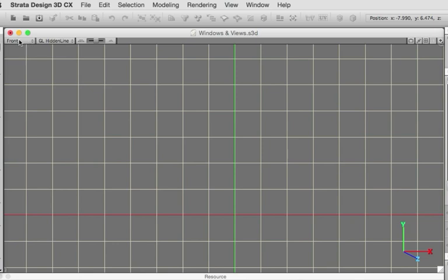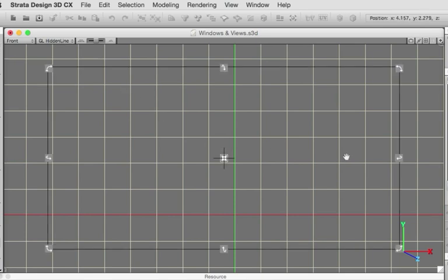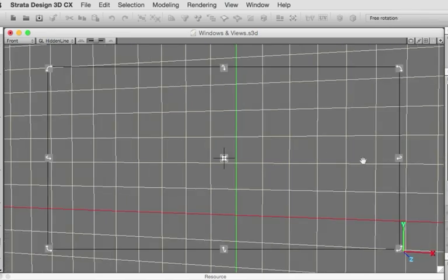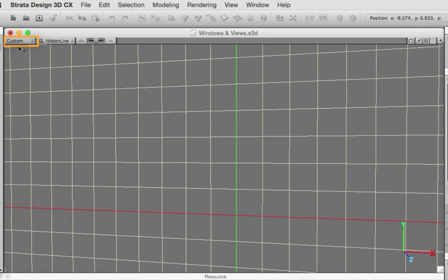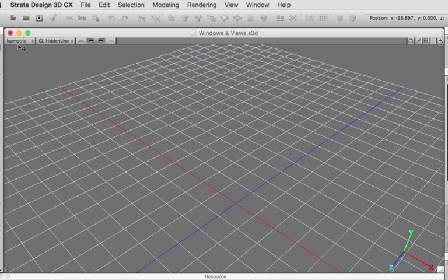You'll remember that you can always create your own custom view orientation by using the Move, Rotate, and Zoom tools from the tool palette. I'll rotate the view using the Shift and Spacebar keys. You'll notice that the View Orientation menu now says Custom. I'll use the backslash hotkey to change back to the 3/4 angled view, known as the isometric view. Design 3D offers a variety of ways to look at your model.